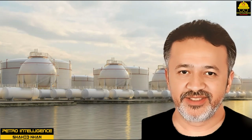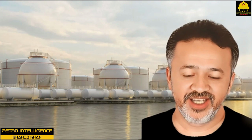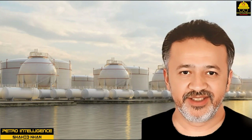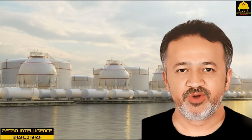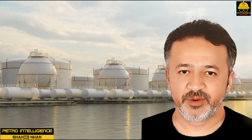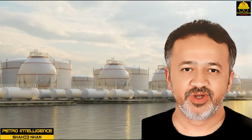The inspector studies the condition peculiar to each piece of equipment. The nature of the material contained, the pressure, temperature, flow conditions, and other factors may cause or contribute to deterioration of equipment. Familiarity with operating conditions and knowledge of the materials of construction are essential.